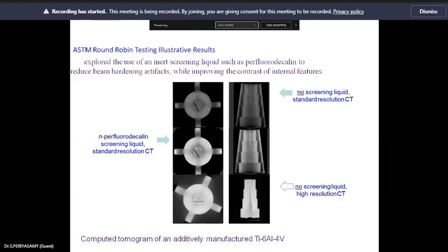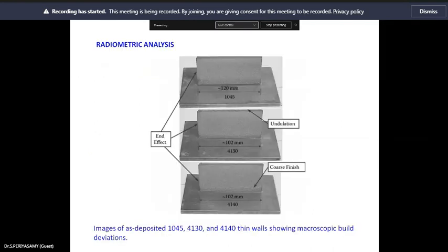So the thermal stress, residual stress, and the microstructure you can refine using different types of scanning strategies. Here the scanning or deposition of the material will be at different values. The fill contour offset, that is the inner side, is a fill. The number of layers, each layer will be in a different direction. The particular one represents the parameters that can be altered to improve the quality.